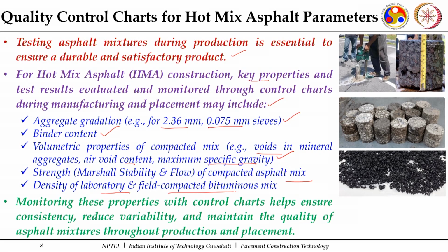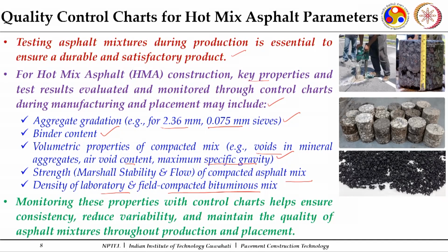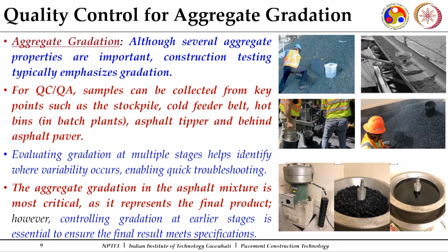Density of laboratory and field compacted, that is, in field also we measure the density, we can do the determination in the lab also. Monitoring these properties with control charts helps ensure consistency, reduce variability, and maintain the quality of asphalt mixtures throughout the production and the placement. So, this is an important aspect.